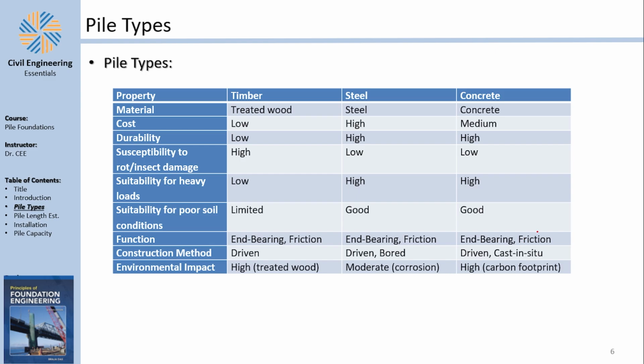Well, they all share this by end bearing and friction. Usually timber piles are driven. Steel piles are usually driven, but they can be bored. And concrete is driven or cast in situ.